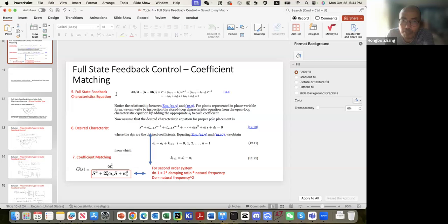So this pole placement, although theoretically very interesting, can be challenging for real world systems. Why can it be challenging? Because it ideally solves low order systems. Let's say it's third order, or maybe at most fourth order. To solve a 12th order system is nearly infeasible. In that case, you need to use LQR or MPC, okay?